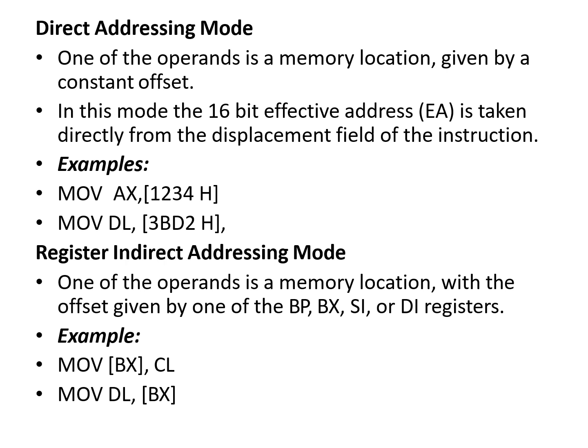Then as usual, this offset value is added with the segment register address. The segment register starting address is multiplied by 10, and along with it the offset residing in BX, BP, SI or DI is added. Finally, the physical address is calculated.